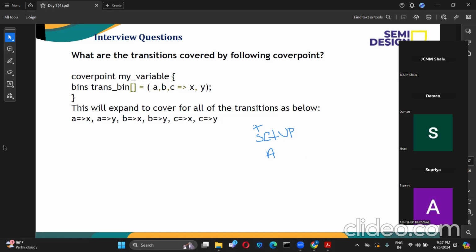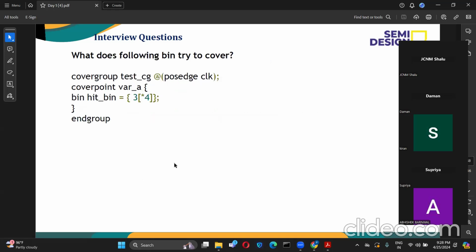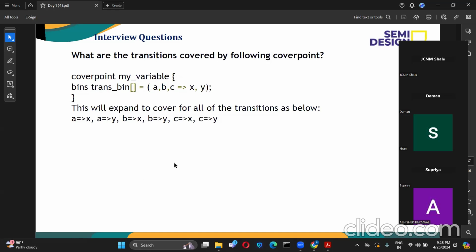In our cover, we can. The possibility is there, so it is allowed by SystemVerilog. We can have the same values on the left side and right side of the implication operator. In a transition, don't call it an implication here; you can call it a transition operator. In an assertion, it is implication.